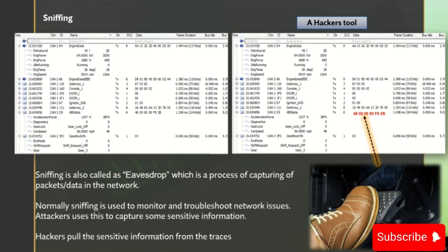In turn, he can note it down. He can have the ID, for example, the CAN arbitration ID, and with that he can play around. Likewise, he can understand all the necessary information. Let's say, for example, just by unlocking the door, which message is getting published or activated. That message's values he can hack, manipulate, and he can perform the hacking of the vehicle. Understood?